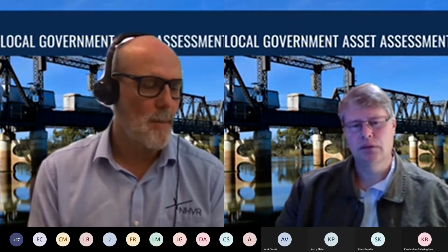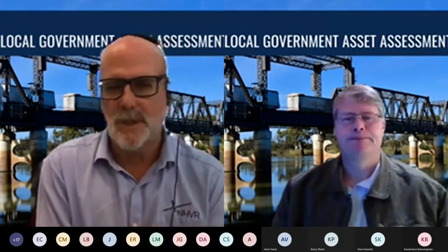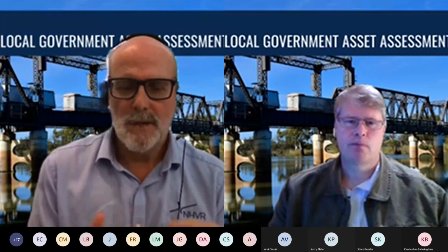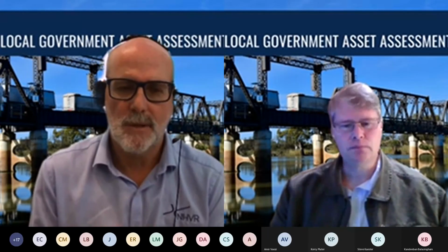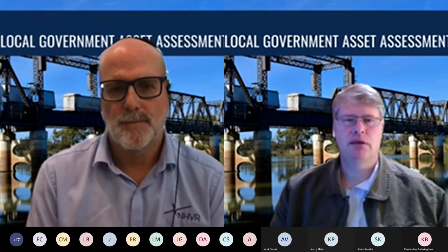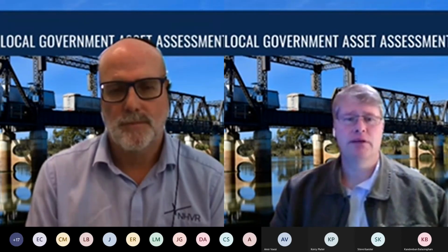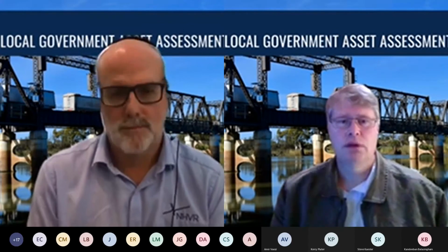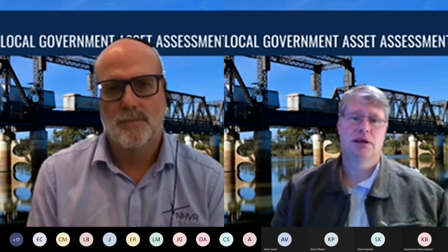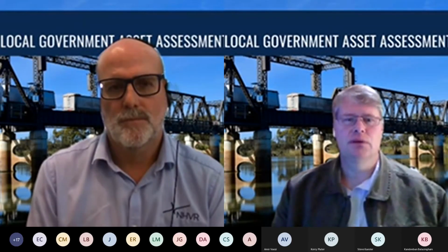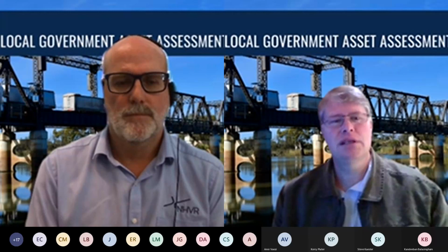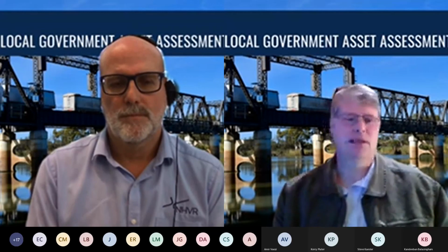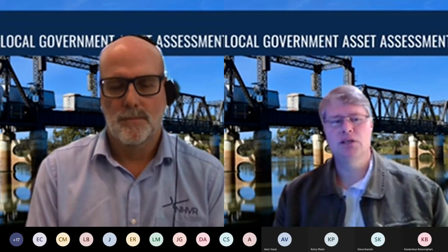Yep, I agree. Just one other quick point. You talked about superseding of assessments. In the case where the condition of an asset has changed, what does that mean in relation to assessments that may have been undertaken in the past? Yeah, it's exactly the same thing, because if you have degradation in condition that affects the percentage of a reference vehicle that is suitable, then we have a new reference vehicle essentially that we would use in Tier 1 assessment, because the percentage of the vehicle that could cross safely would reduce. That's like improving your Tier 2 assessment by considering condition. Then when we go back and do Tier 1, we have basically the same reference vehicle, but with a lower percentage. So definitely condition supersedes previous assessments.